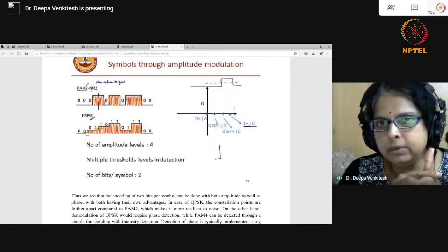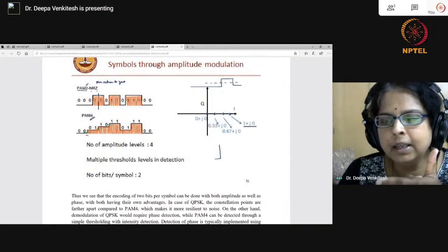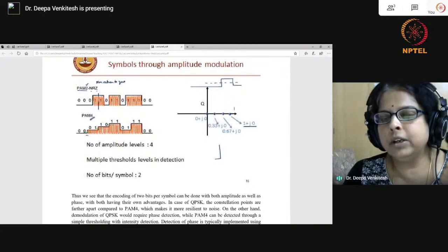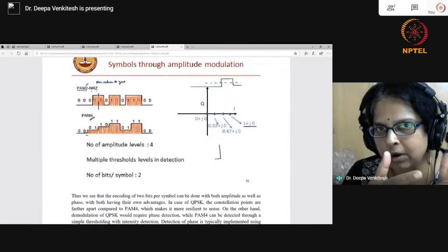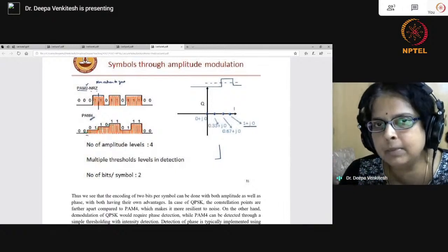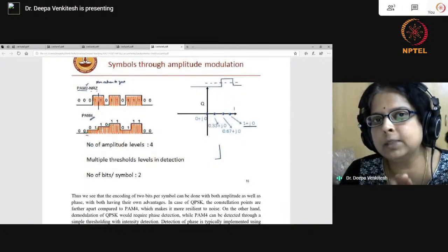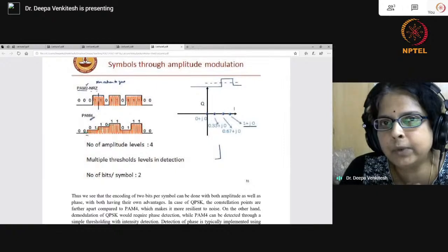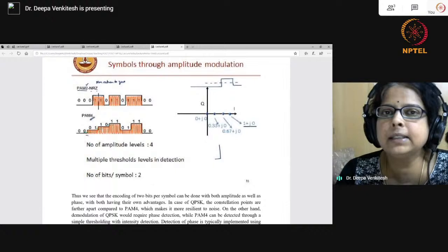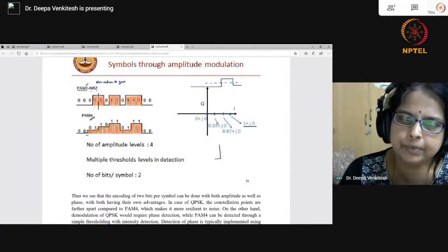First criterion is attenuation in the fiber. Second criterion is dispersion in the fiber, right? If you want to go for very long lengths, you want your attenuation to be small because you want the loss to be small, and you want your dispersion to be minimal so that the pulse doesn't spread out. For those who do not understand what dispersion and attenuation are, please wait. It is coming up in the next weeks. Now, it turns out that 1550 has minimum attenuation, whereas 1300 has minimum dispersion.